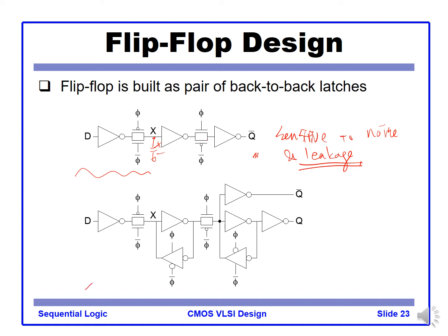So we prefer a fully static implementation, shown here. We have a first latch here and a second latch. In this example, at the input we have the inverter there. In the second latch, we didn't put the inverter because inside this latch we already have an inverter in the previous stage, and they're tightly placed, and there's no unknown parasitic at the input.